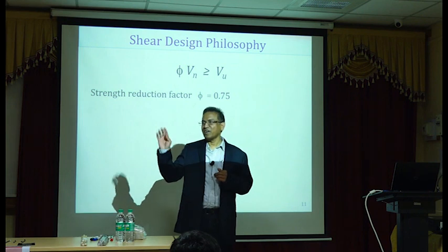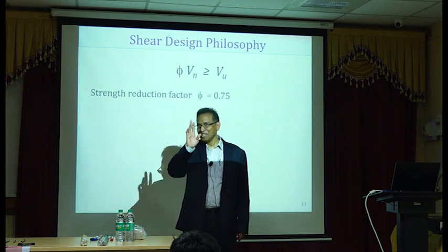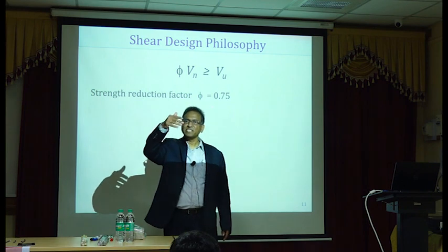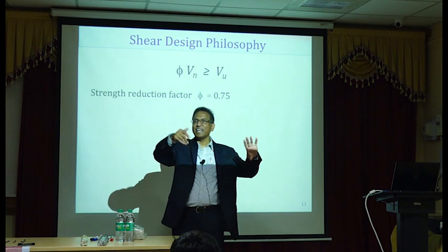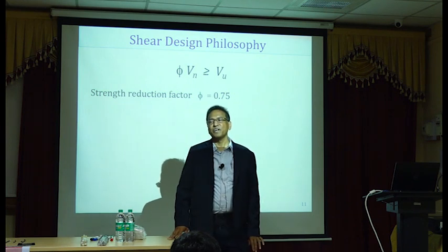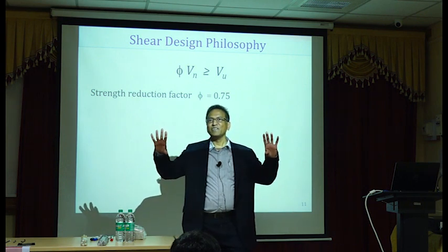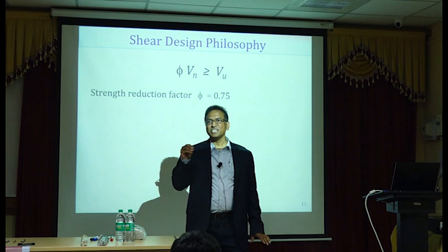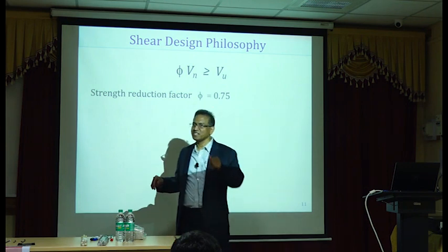Okay, I'm done, I have to go back and do whatever. So you stop the test and go. That's for flexural failure. It takes a lot of deflection, and eventually it will fail. However, for a shear failure, you just take your eyes away, don't look at the beam for a couple of seconds, and it would have failed.